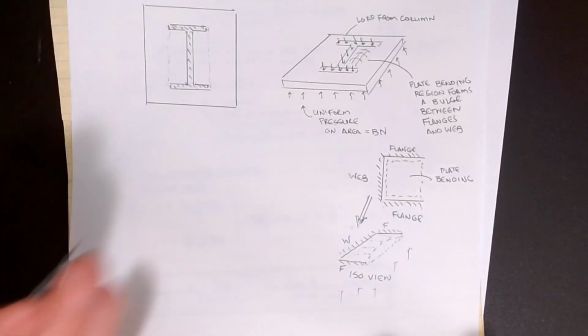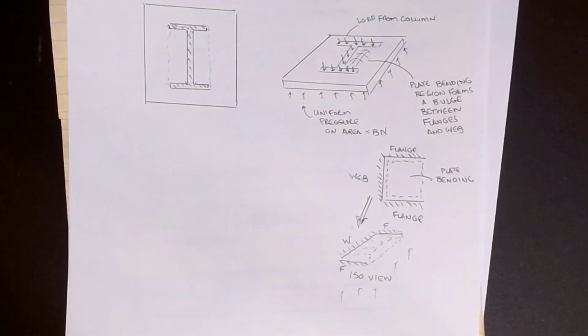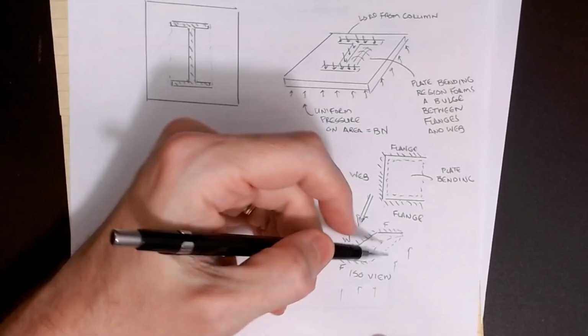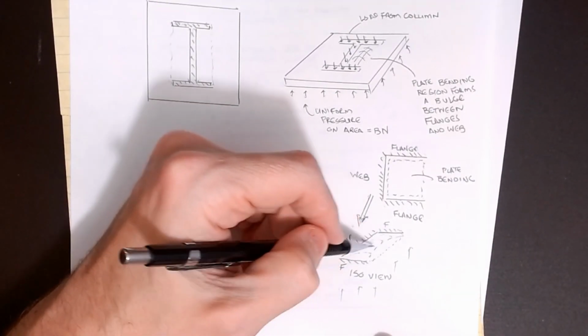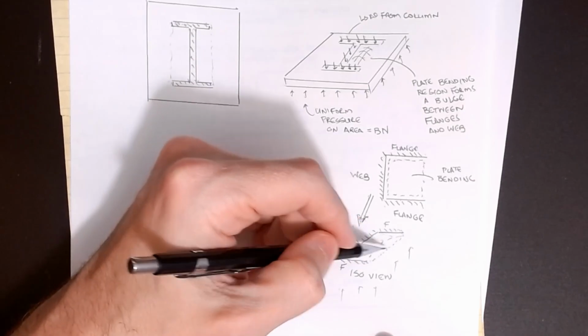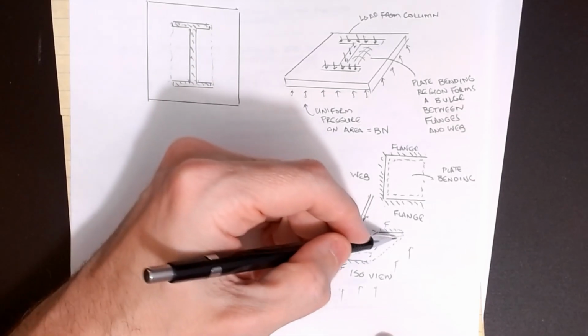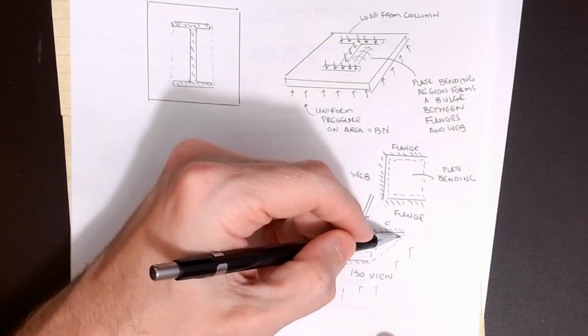Okay, if you've ever taken a sheet of paper and grabbed three edges of it, and then put some sort of load on it, that fourth edge wants to curl, right? It doesn't hold perfectly straight. So there's some flexing or flexure that happens, a two-directional flexing problem that starts to occur. And that's what we're looking at when trying to calculate this.